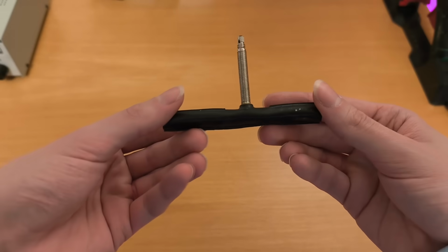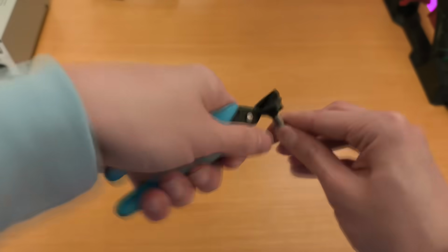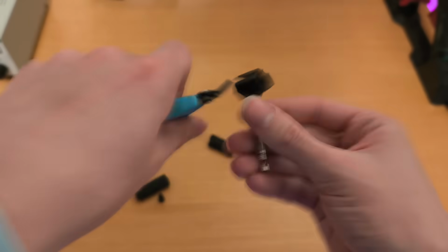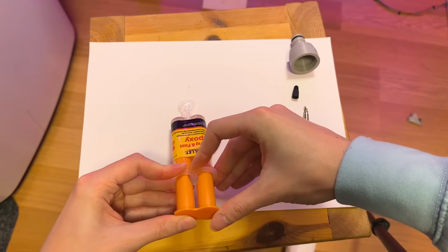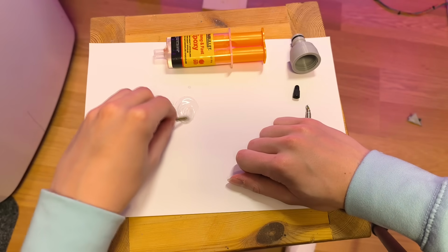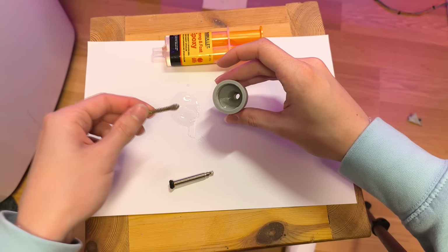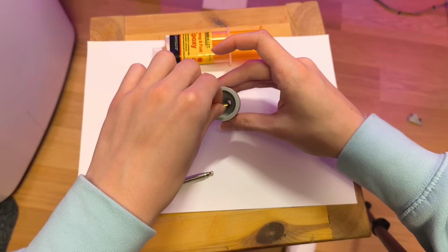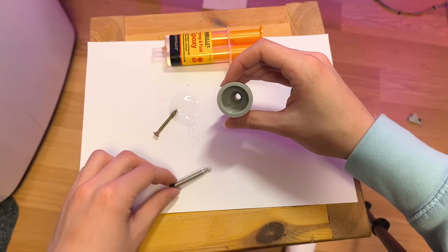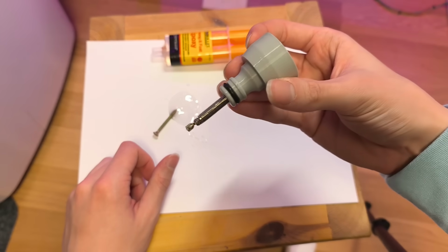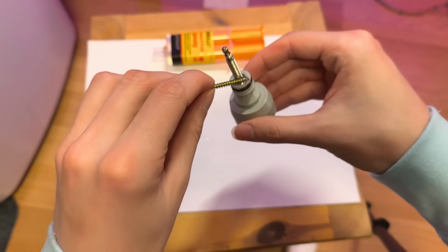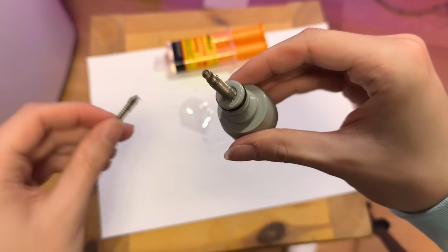For pressurizing the air tank, I used this Presta valve, which I removed from a broken inner tube of a bicycle. I then glued the valve onto one of these 3D printed bottle cap to garden hose adapters, as I realized that it was very easy to glue the valve onto it. I glued it on with 2-part epoxy glue for a strong and airtight bond. The epoxy also seals any cracks and cures quickly, which makes it the best option for this.